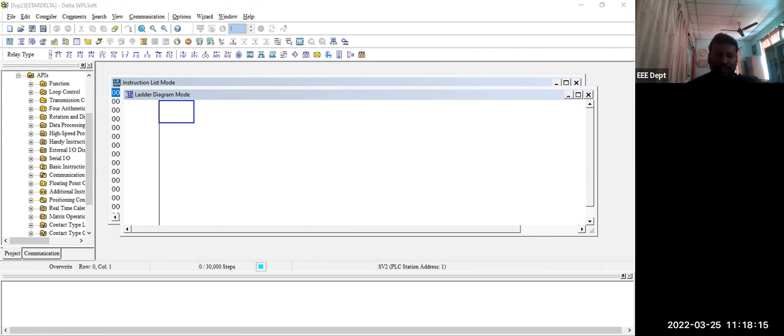So in this case, there are 3 modes of operation. At starting, the stator winding is in star connected mode, and after the motor reaches 80% of the rated speed, the stator winding connection is converted to delta mode of operation.